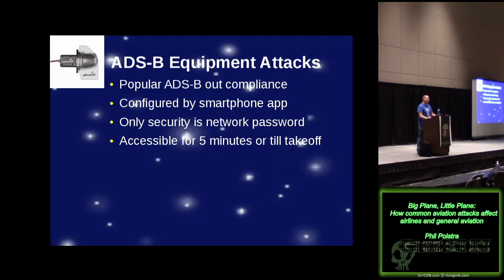But this particular airplane, someone upgraded it so that these little lights flash. So I had to find this stupid flasher unit and then disable it, which, I ended up removing seats, crawling up under the dash. And that was the biggest pain in the butt of this thing. So, if I hadn't had to do that, you're looking at probably an hour and a half or so.